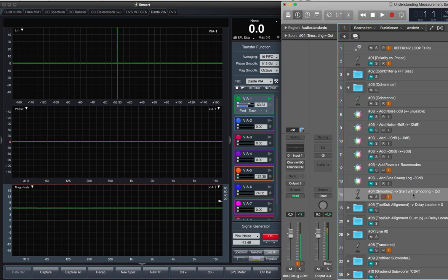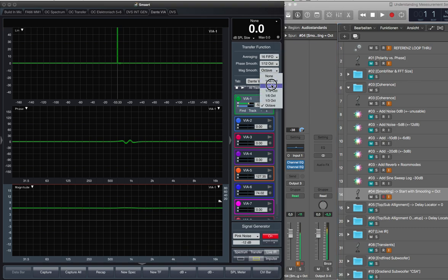I'm measuring a speaker, and the speaker gives me a magnitude like this. And what you do to correct this is you introduce an EQ. And perfect, I'm done, good job. But then it sounds terrible. And I switch back to 1/48 octave, and you see this is a problem, and this is my solution. Yeah, and that doesn't match perfectly, and bad job.